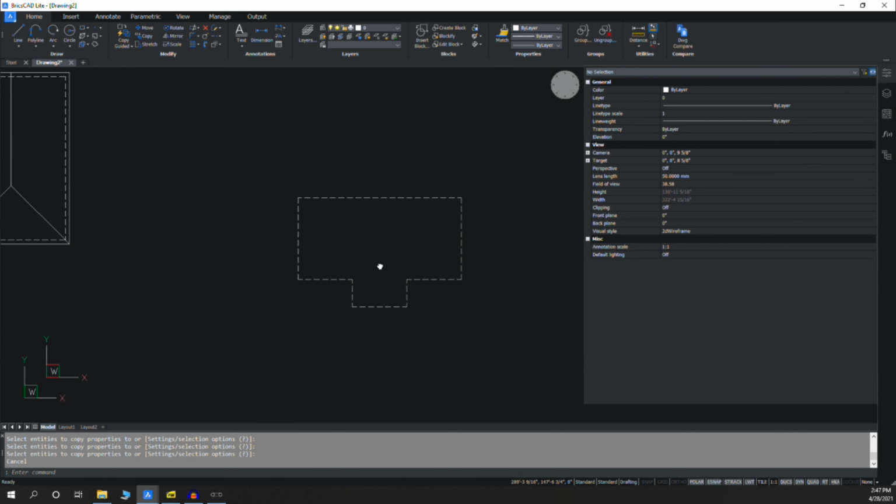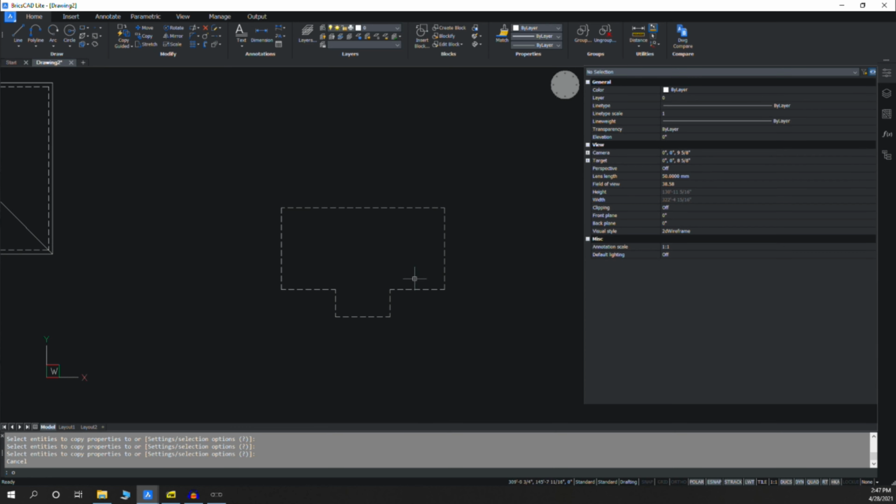So now we have the roof outline. So again, let's say that we want our roof to have an 18-inch overhang. So I'll hit O for offset. I'll type 18 inches. And if you notice down here, it preserved my 18-inch offset from last time. So it says 1 foot 6 inches.